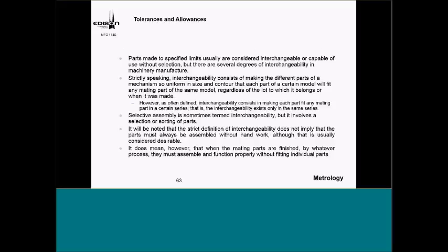Okay, the other thing I try to hit really heavy here is the interchangeability. In other words, if they're made within the specified limits, they're considered interchangeable or capable of use without selection, but there are several degrees of interchangeability. And again, what we're talking about, are we looking at the same model? A certain model may fit. I talk a little bit about aftermarket here, that sometimes it may not fit because it's not exactly per the standard, if you will, or accurate per the print. Sometimes you may have to do something with it.